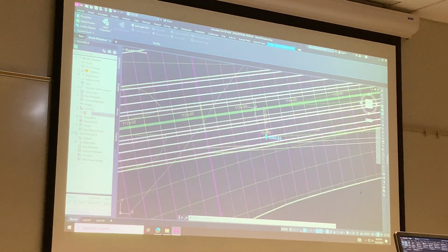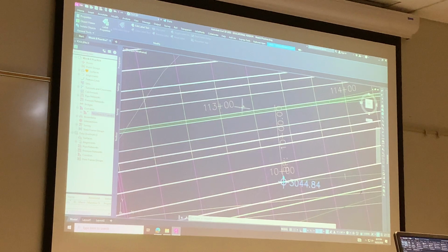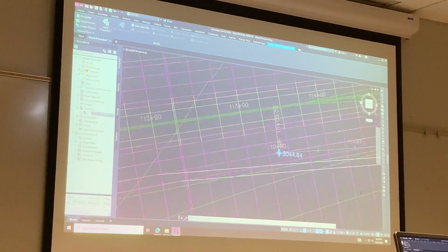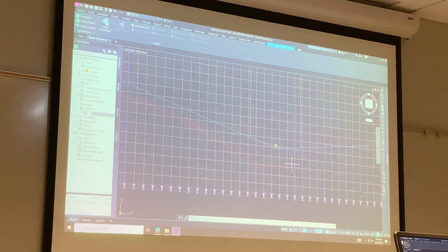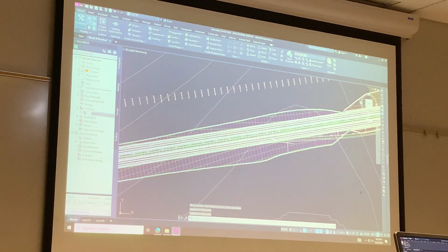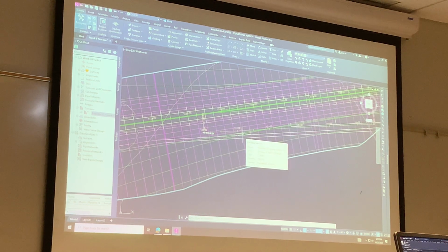And then I could look at the relative station over here and see, okay, it's at a station of 113 something. I'd have to place a label. We did that last week, right? We placed a label here, found what station, went down here to that station, and roughly found the grade. So that's why I recommend do everything with the main line first.